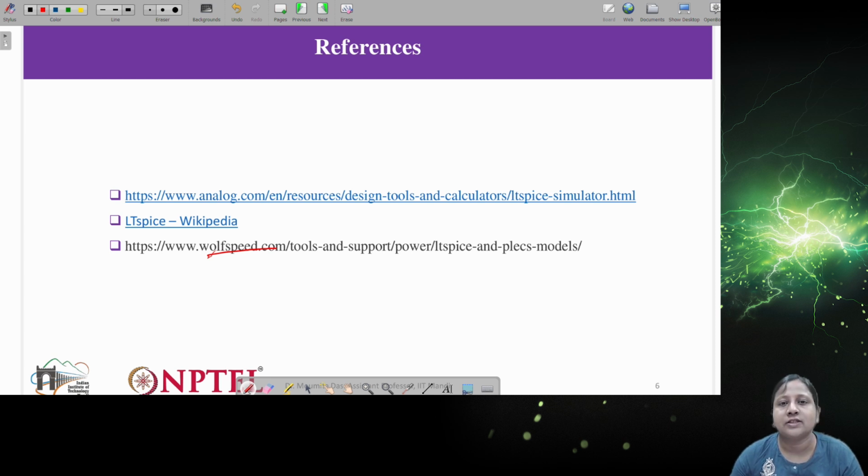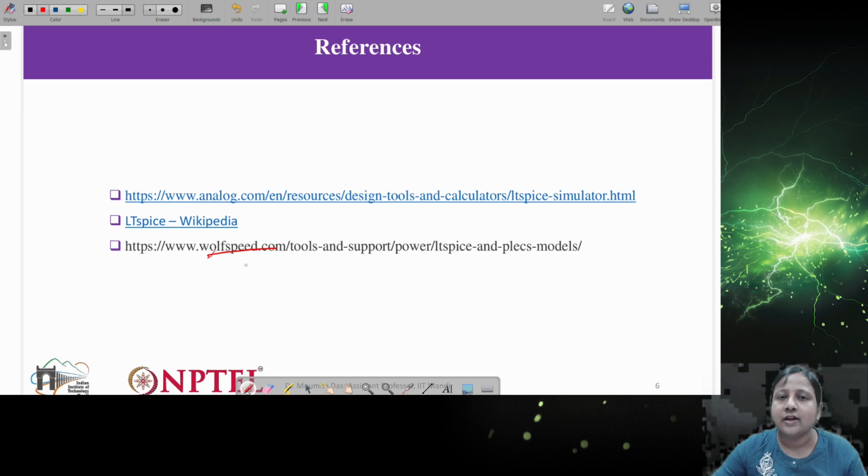You will see some differences, because the parasitic parameters of the GaN and the silicon carbide will be different. Even if you keep the same conditions, some differences will come in the switching or the gain. Some small differences you will be able to notice. Just check that to understand the basics of this simulation, and how to use wide bandgap devices in any kind of converter for simulating the converter. You can get this from these two lectures. Try it by yourself at home. Okay. Thank you.